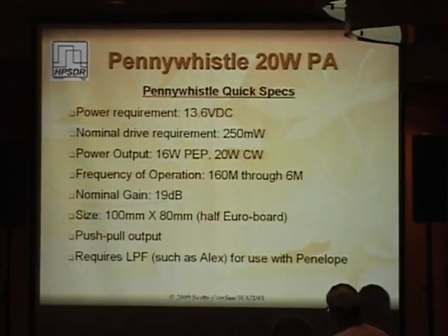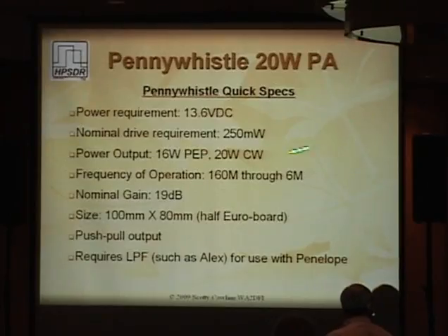Runs on 13.6, and by the way, if you have an LPU, there is an internal connection on the LPU just for Pennywhistle, so you don't have to run an extra cable through the back and try to find a place to snake it through. 250 milliwatts drive, 16 to 20 watts, depending on your favored mode. Operates all the way up through 6 meters, about 19 dB of gain. You will need a low-pass filter of some kind, whether you use Alex or something of your own.